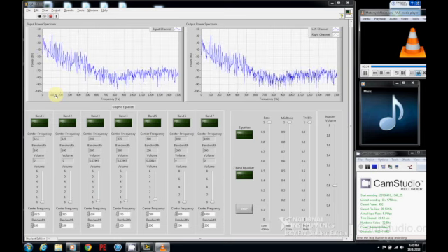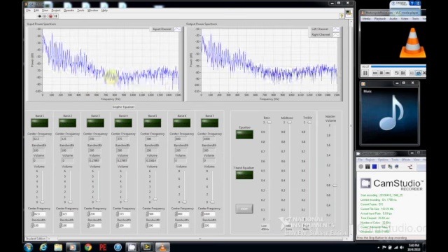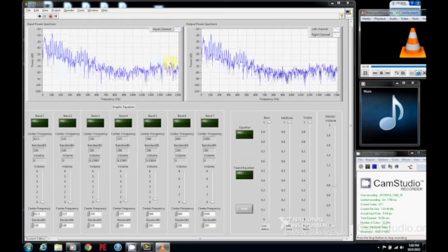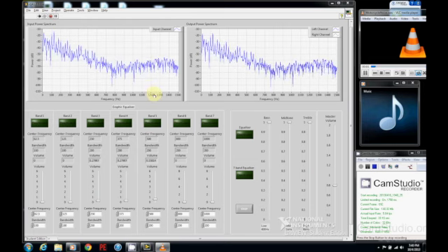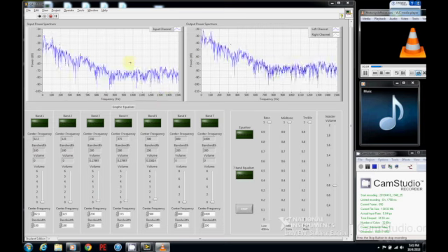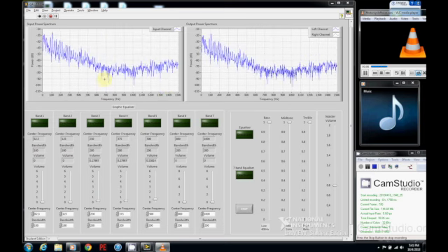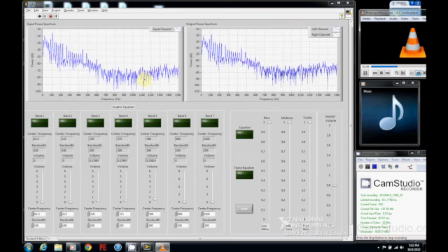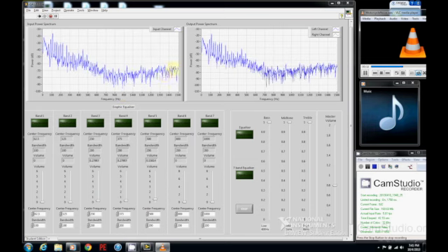But before that, another characteristic you can see is that approximately 600 Hz and beyond, the spectrum of the engine noise falls to a relatively low power decibel level. Hence, we decided to leave this region untouched and unfiltered, since it is not going to affect the music signal extensively, and in doing so it will actually preserve the original music content.